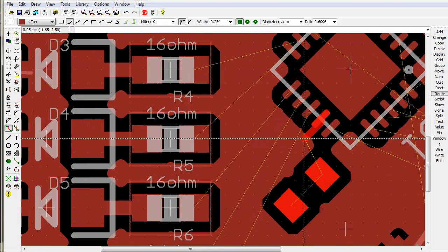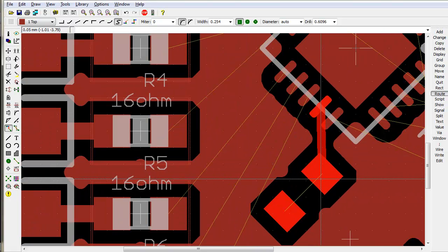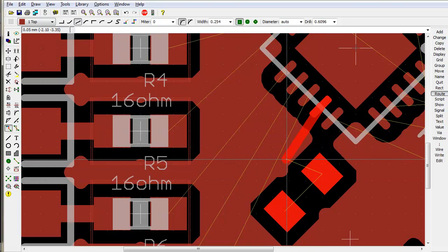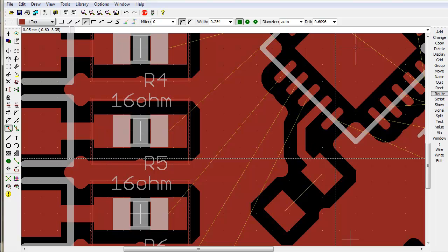And now you can see that we have that fine kind of control. It's probably a little bit too much, to be honest. And now I'm going to move it around. You'll see that Eagle will try to map it the way we want, but none of the defaults really work. So what I'm going to do is go into this mode and bring it out to about here so the lines are all nicely even, and just bring it in, and that's it. That's how you route a wire.